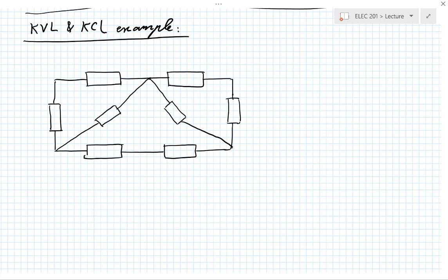And to do so, you also have to pick a polarity convention. So voltages and currents are properties that have a sense of direction or polarity. So give a name to each element's voltage and current, and write all the KVLs and KCLs. See if you can do it on your own. This is our first example, so you might not have seen things like this before, which is fine. Give it a little bit of a try, and then we'll do it together.